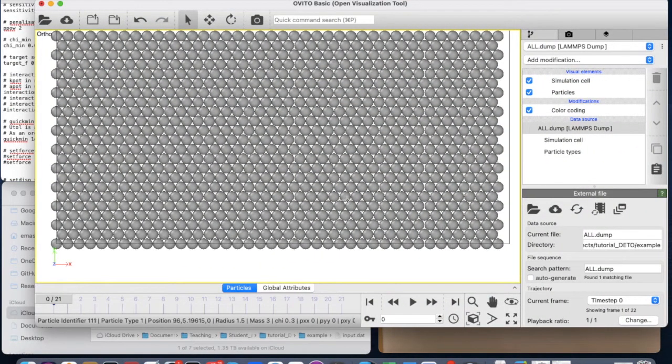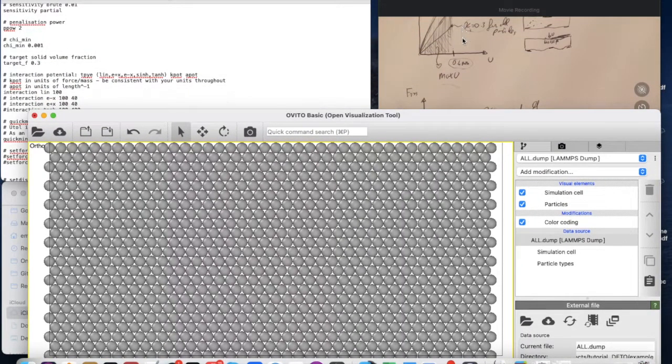So let's once again peep into the future and consider what the code is doing every time that we run an optimization. We said that during an optimization, since we are working with imposed displacement, the system will start from zero displacement and zero force consequently, and then it will progressively increase the displacement, measuring the corresponding force until reaching the imposed displacement. So for every set of values of xi, we expect that the code will perform a full simulation with a progressively increasing displacement and correspondingly increasing force.